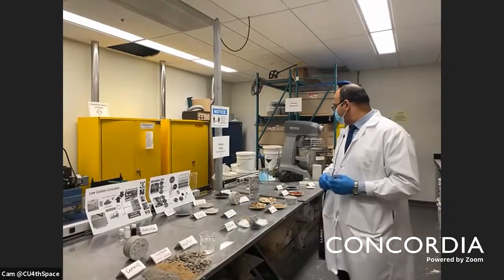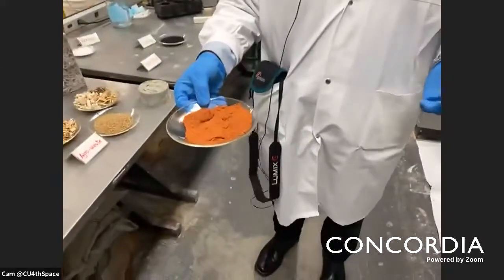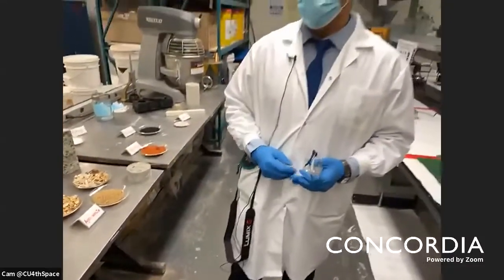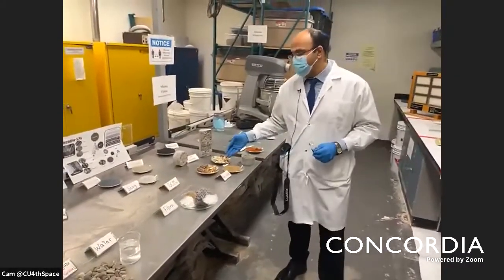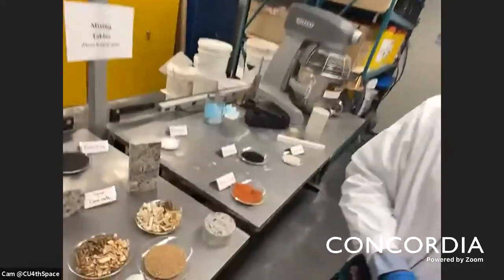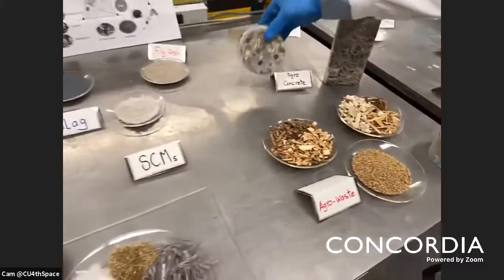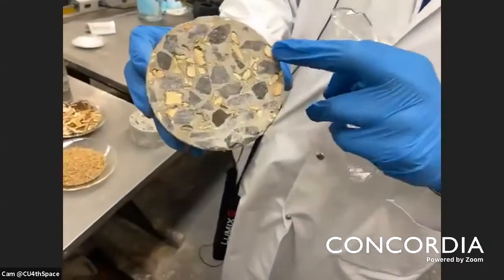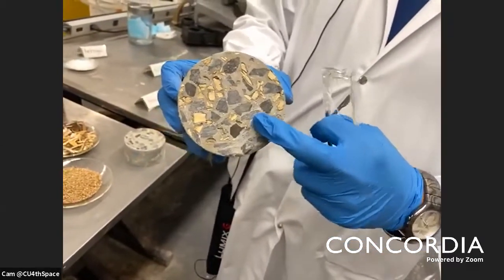And this opened the way for us to implement different types of waste. For example, we have here the red mud, which is coming, as you know, from aluminum production. We can use it. The other way that we try is by replacing the aggregate. And as you can see here, we have the agri waste, which is actually agriculture waste, of different types and different sizes. And we try to implement it inside our concrete. As a result, we have here what we call agro-concrete. You can see here the agri-waste particles and also the natural aggregate that had been used.